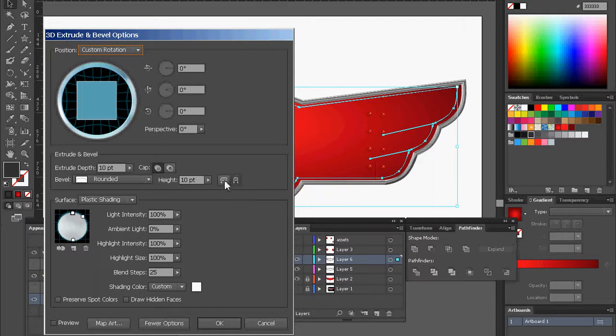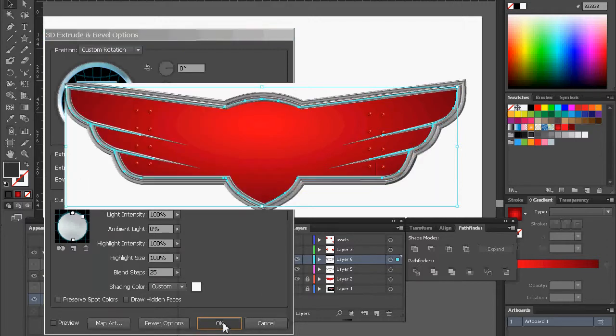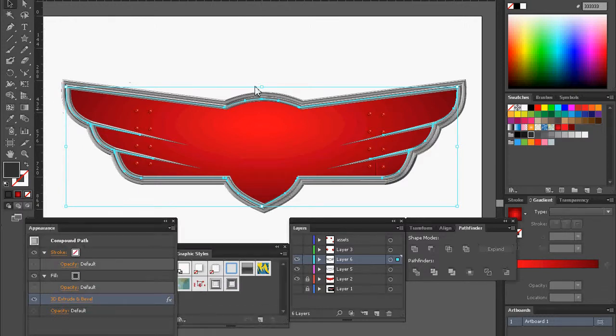You see these sharp lines here. In the logo, it's not sharp at all. Even though I don't feel like this looks too bad, I'm going to show you how to go ahead and fix that. I'm going to zoom in. Let's get our direct selection tool, and these things both have 2 points for each tip. I'm going to select the top point with the direct selection tool, and then I'm going to tap up once, tap up twice, and the third time is a charm.